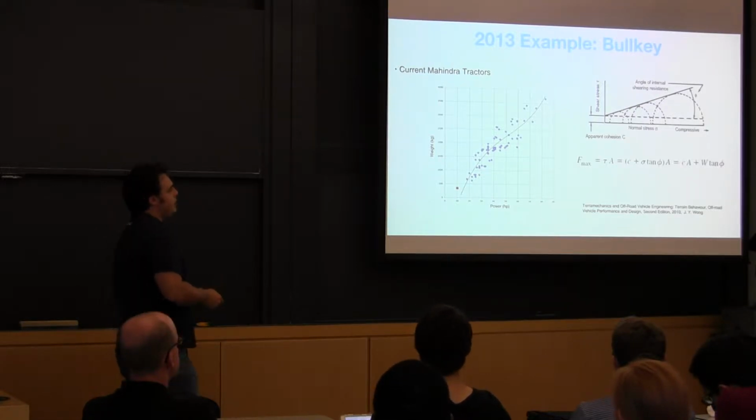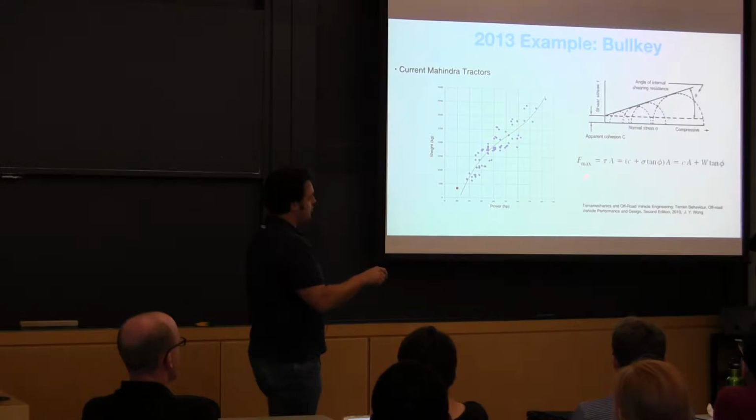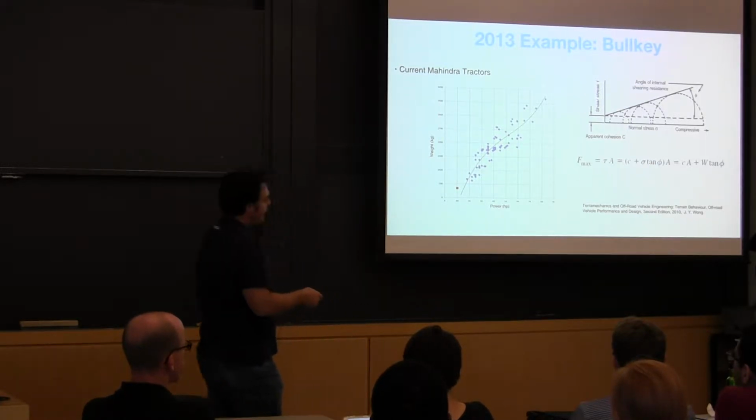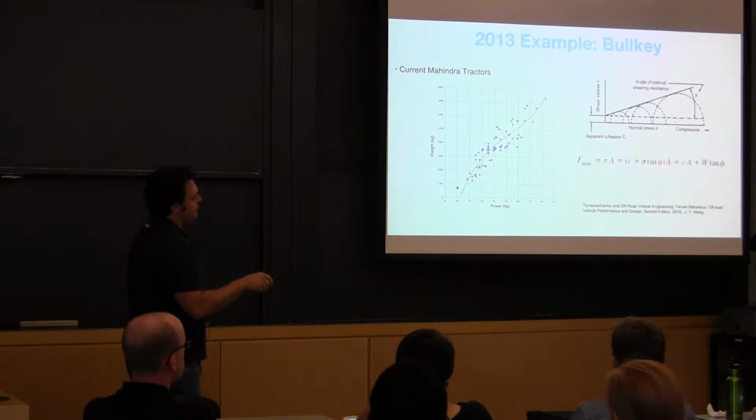They also went in and looked at the terramechanics of what dictates how much pulling force you can generate with a wheel, traction force. And so they looked into these soil mechanics principles and understood how things scale relative to each other. It's like area of the tire and friction angle of the soil, et cetera. And they actually read the sections of the books on this stuff.